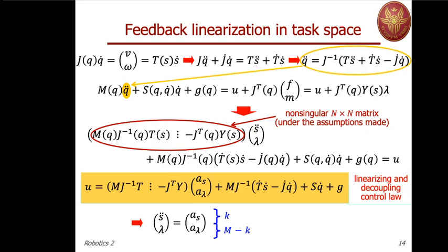So if you had taken S and lambda as output of your nonlinear system, and you would have applied the inversion algorithm that we have seen for the Cartesian control in the free space, you would have ended up taking enough number of derivatives of your output until the input appears, and in fact we have now a difference, because we have to differentiate the motion output S twice until the U will appear, and in fact this is what we have seen from the above equation.